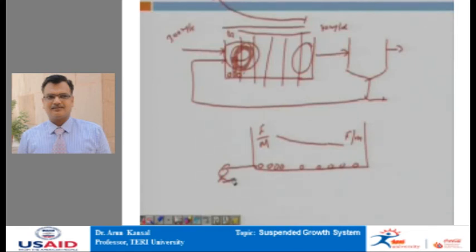And secondly, we are avoiding over aeration, and by avoiding over aeration we are limiting the growth of nitrifying organisms, because these nitrifying organisms exert more oxygen demand and it also results in the denitrification or sludge rising problem in the secondary settling tank. So, this is the basic advantage of tapered aeration, that is operating cost reduces, oxygen utilization is more efficient and the sludge rising problem is reduced because we are not allowing the nitrification to take place.